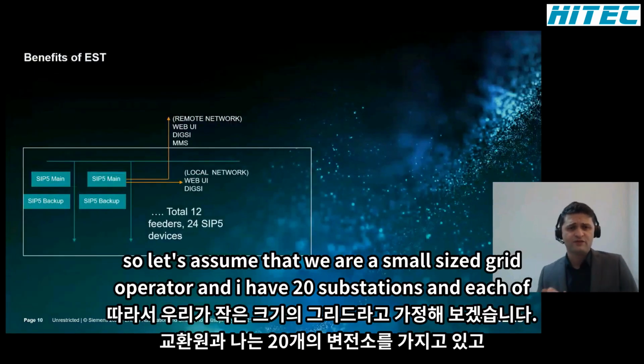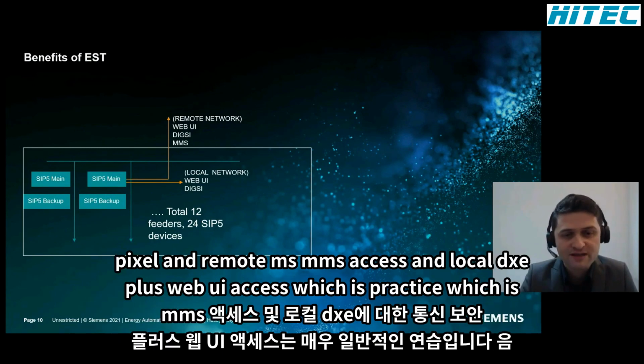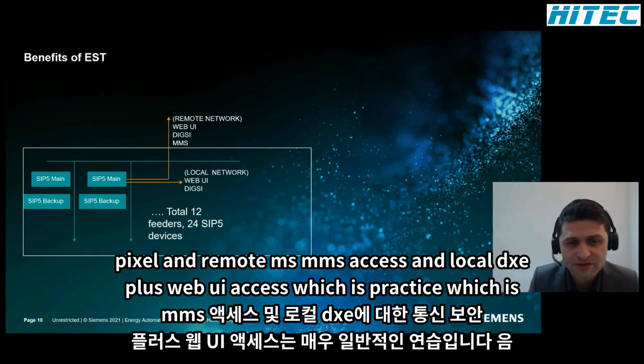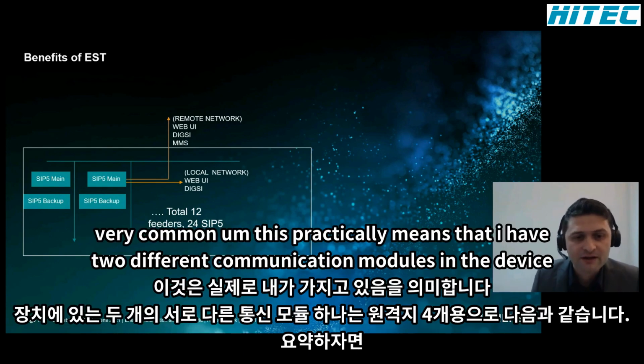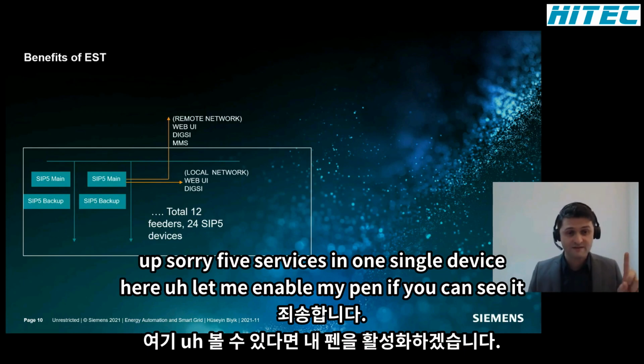So let's assume that we are a small-sized grid operator, and I have 20 substations, and each of those 20 substations has 12 feeders. I want to secure the communication for remote web UI, remote DIGSI, and remote MMS access, and local DIGSI plus web UI access, which is very common. This practically means that I have two different communication modules in the device, one for remote, one for local access. And if we summarize this, I have a total of 5 services in one single device.